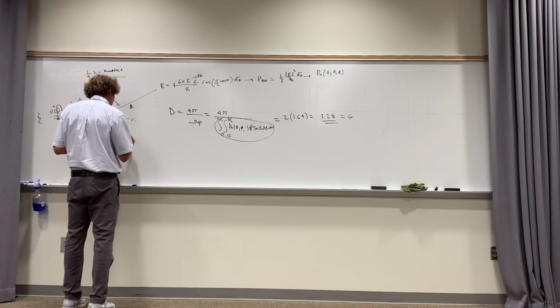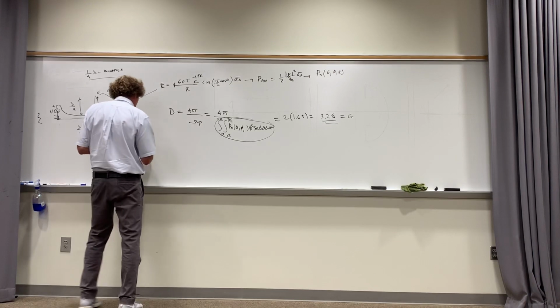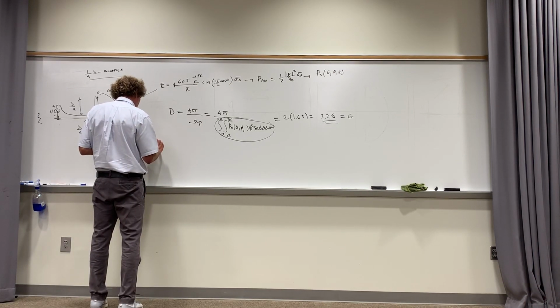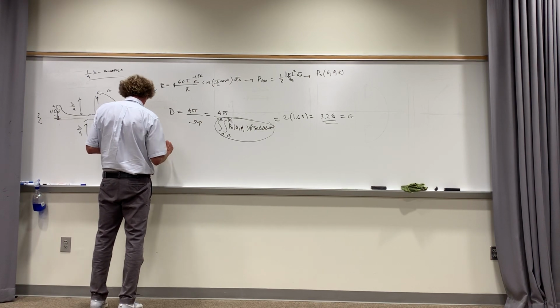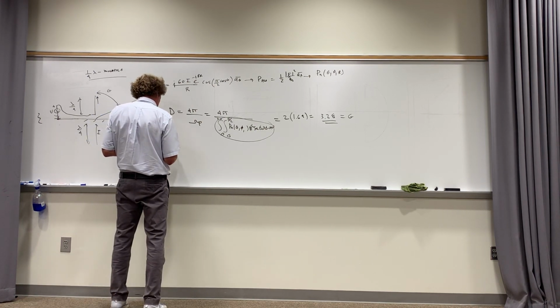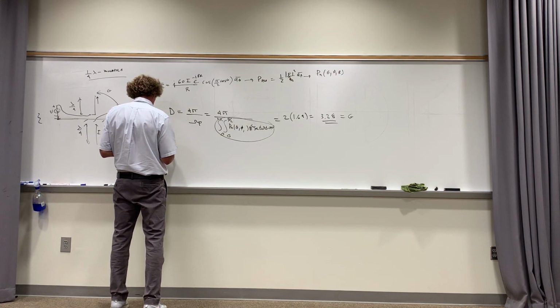If I say P rad for the monopole, I'll call it lambda over 4 monopole, is equal to 1/2 P rad for the dipole, the lambda over 2 dipole. That means the P radiated is going to be, if you remember for the half-wave dipole, they gave the power radiation formula, but they found out it was equal to I squared, right?